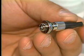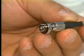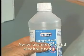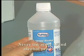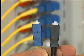Swabs are usually used dry, but in cases of severe contamination can be saturated in solvents such as isopropyl alcohol to break up stubborn grime. If alcohol is used, be sure to use reagent-grade 99% alcohol rated for cleaning fiber optics, not store-brand rubbing alcohol which can contain more than 30% water. When the sleeve has been sufficiently cleaned, we can move on to the connector ferrules.